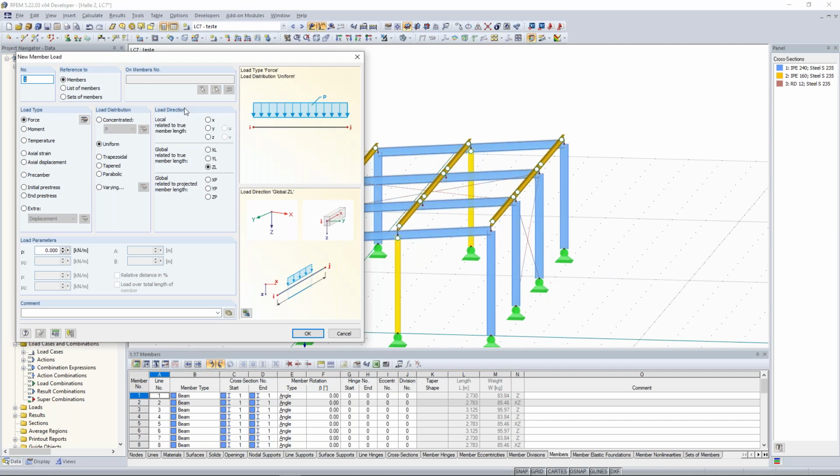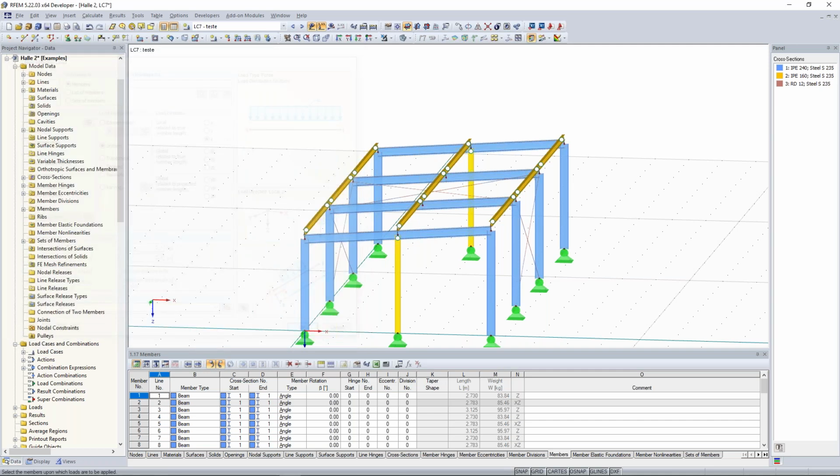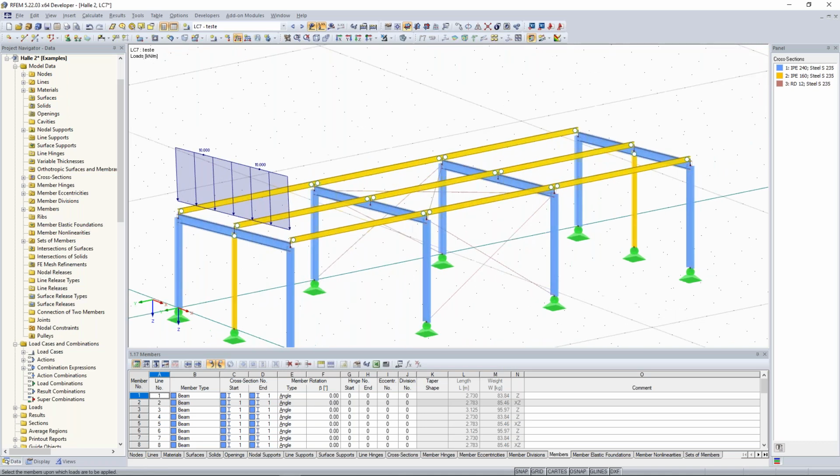And in this case, when I have to consider the suction or the wind pressure at their value, when I want to consider the compression wind or wind compression, I have to add the positive value. And when I want to consider a suction of the wind forces, negative, because it relates to the local orientated z-axis. Yeah, this would be the wind load.